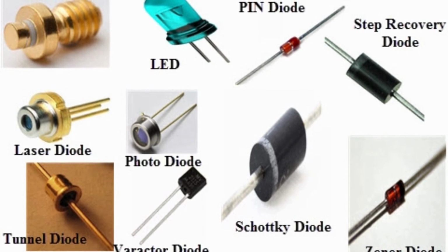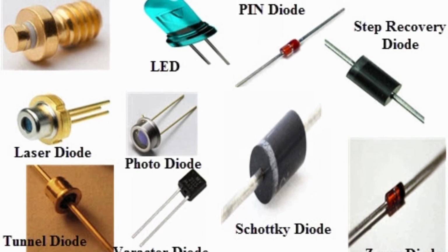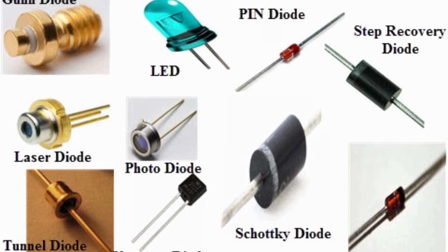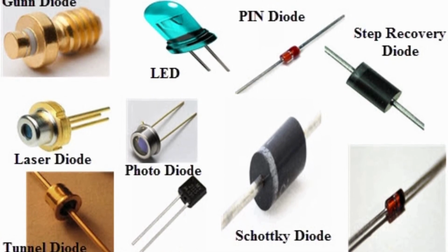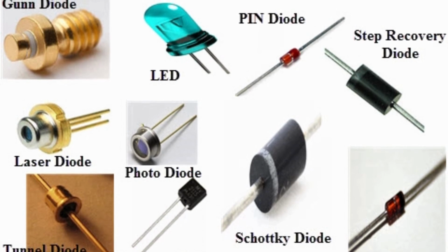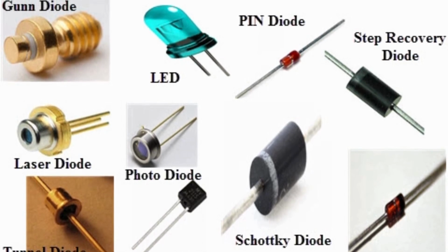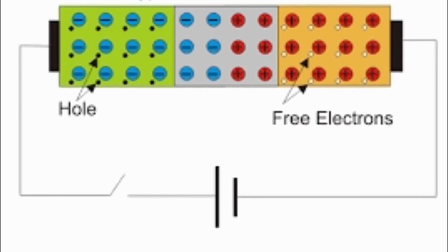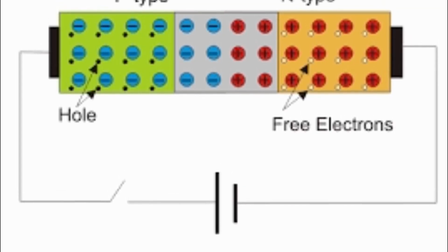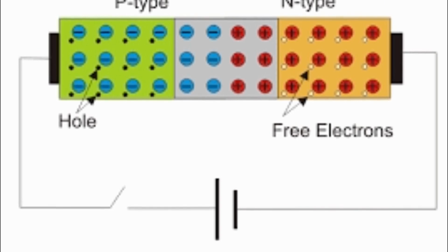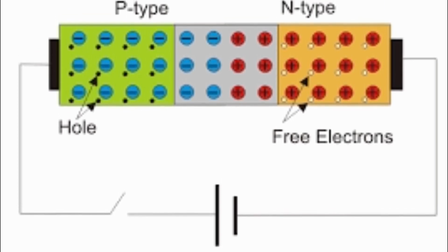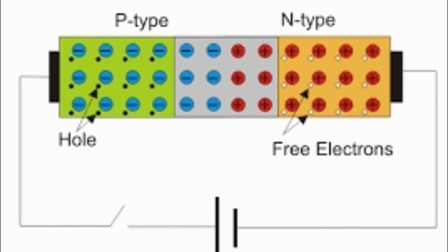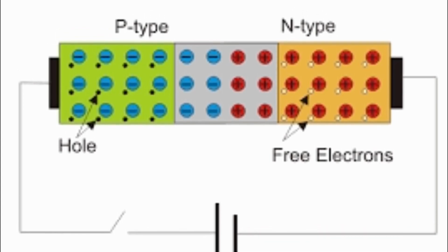Rectification in power supply circuits. Extraction of modulation from radio signals in a radio receiver, and in protection circuits where large transient currents may appear on low current transistors or ICs in interfacing with relays or other high power devices. Used in series with power inputs to electronic circuits where only one of negative or positive polarity voltage is desired.